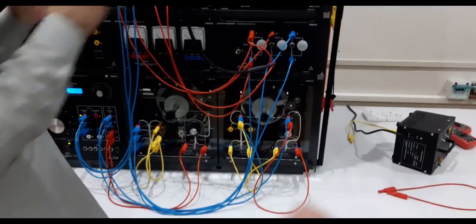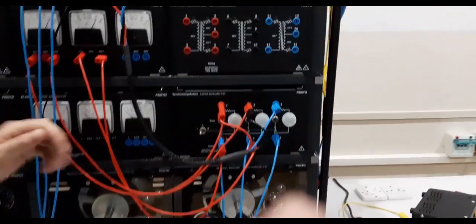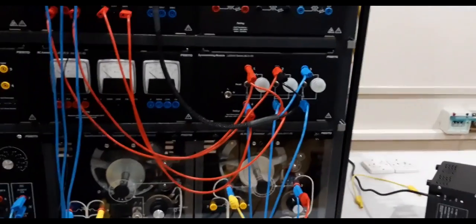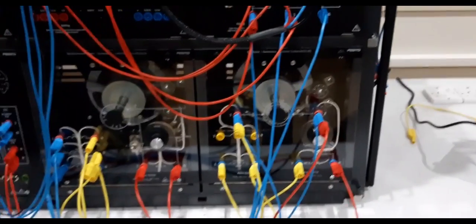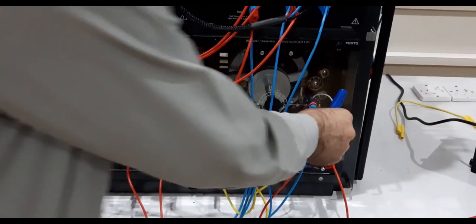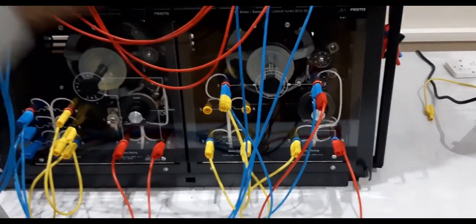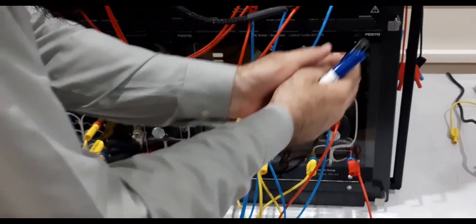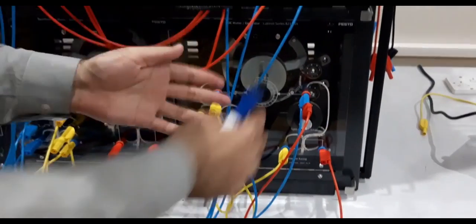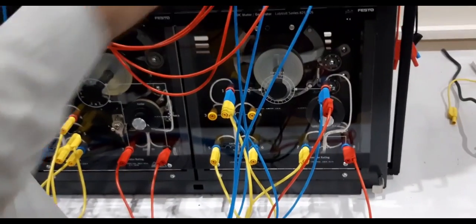So now we have talked about the field variation, and let me talk now about changing the prime mover power. How can we change the prime mover power? Either by increasing the DC voltage, the voltage of the armature, or by reducing the field flux. If we reduce the field of the shunt DC motor, the speed will increase. But because it is connected to the system, the synchronous speed must not change. Otherwise, it is not a synchronous machine.